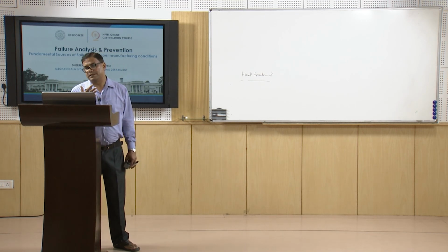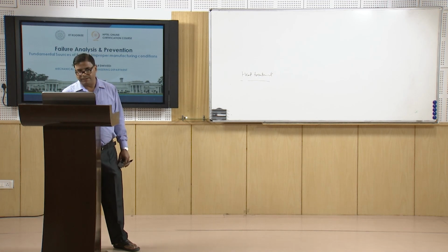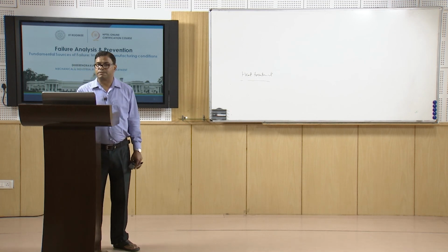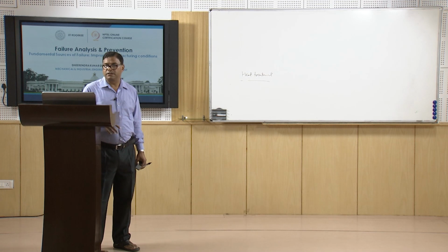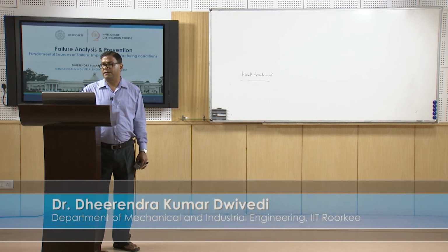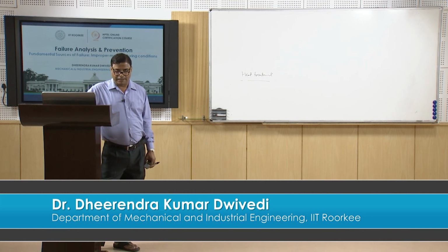Therefore, if the surface is full of ferrite, it will lead to reduced strength, reduced hardness, and increased ductility, especially at the surface. Such unfavorable structural change due to the loss of alloying elements in the form of carbon can lead to premature failure of the component.